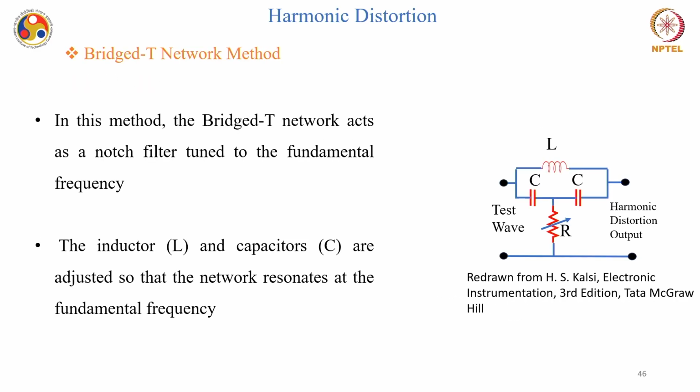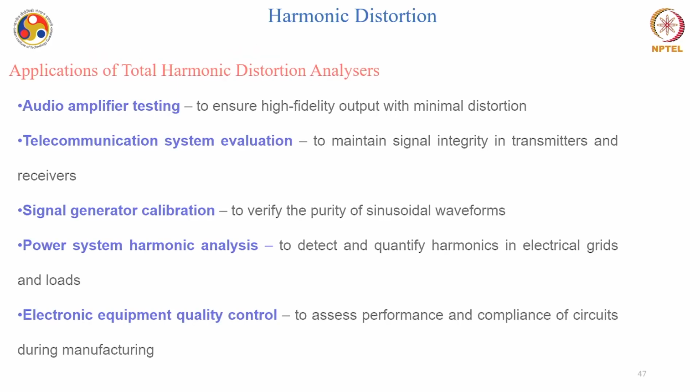In this method, the bridge T network acts as a notch filter tuned to the fundamental frequency, and the inductor and capacitor are adjusted so that the network resonates at the fundamental frequency.